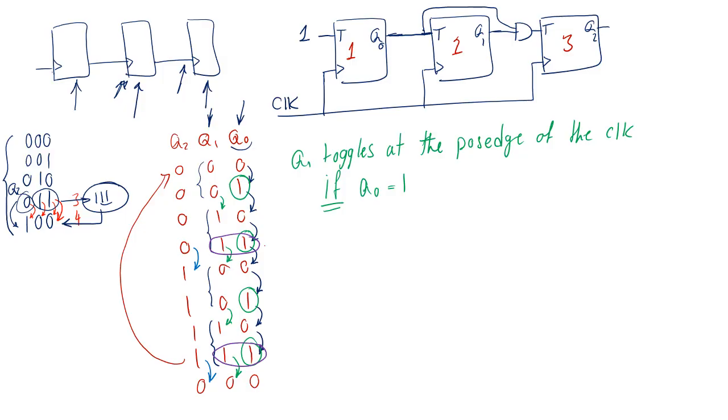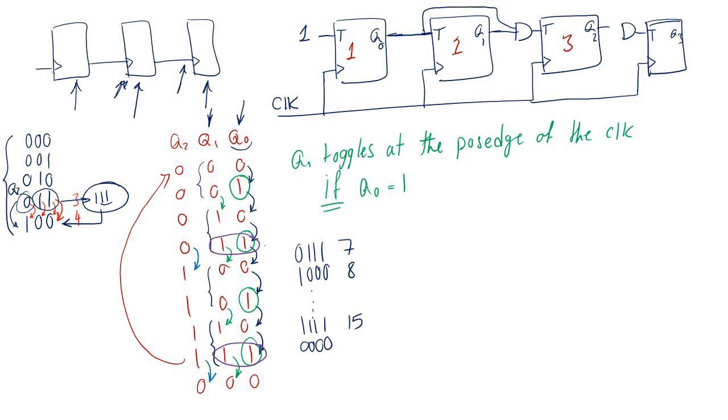So if I had a 4-bit counter, I needed to toggle Q3. Like if I had another thing here, Q3, and this was T3, the clock was connected to this again. I still needed an AND gate, and if you actually look at it, the only toggling happens when I go from 7 to 8. So when I'm from 0, 1, 1, 1 to 1, 0, 0, 0. So I'm going from 7 to 8, or I'm going from 15 to 0 again. So from 1, 1, 1, 1 to 0, 0, 0, 0. So 15 back to 0, right?